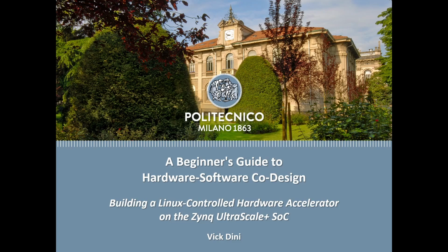Then we tested it using Vitis on our bare-metal hardware. This allowed us to save a lot of time, because if the error we encountered had appeared after building the Linux distribution and testing it on our board, we would have spent a lot of time and resources and would have had to return to the beginning of the whole process.